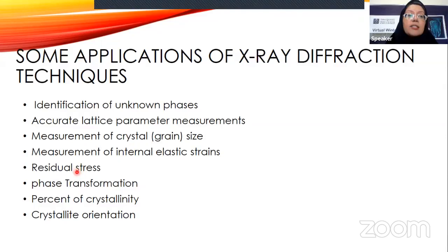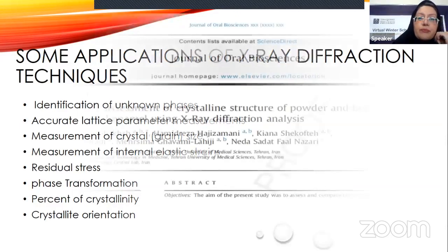X-ray diffraction can help us to measure these residual stresses. Also, we can measure the phase transformation, the percent of crystallinity of materials, and the orientation of crystallites in the material.